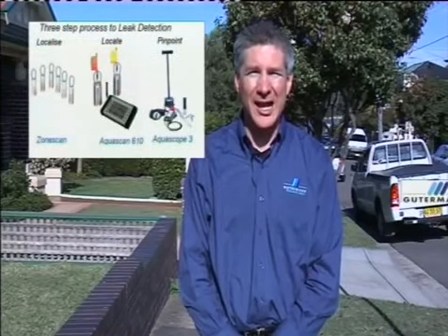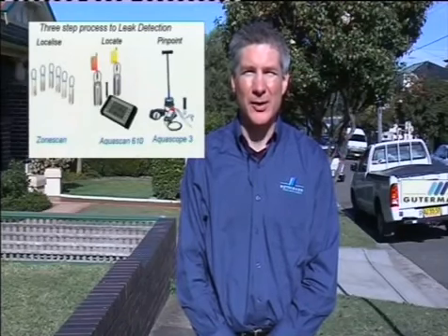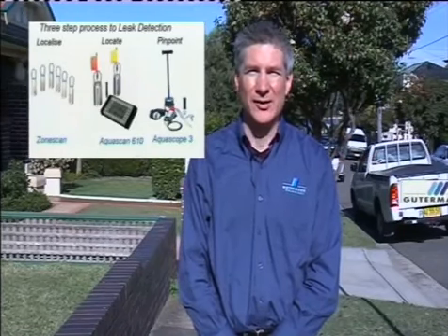In this short presentation we'll explain the three-step process to leak detection, which is LLP: Localize, Locate and Pinpoint, and we'll be using the latest modern technology for acoustic leak detection. Starting with localization, zone-scan noise loggers are deployed on valves and hydrants and left overnight to identify the constant sound of a leak noise when background noise is lowest and pressure is highest.